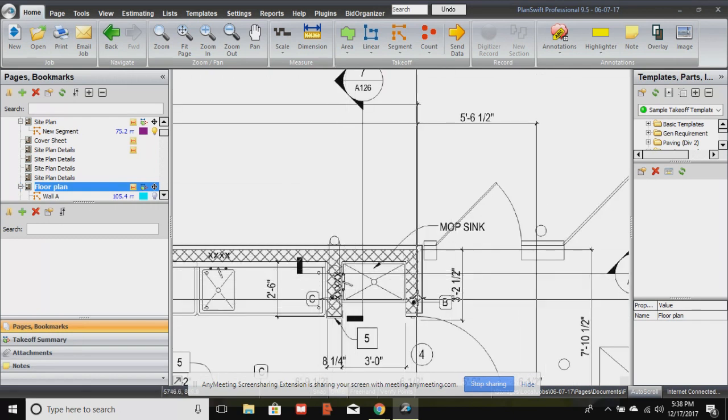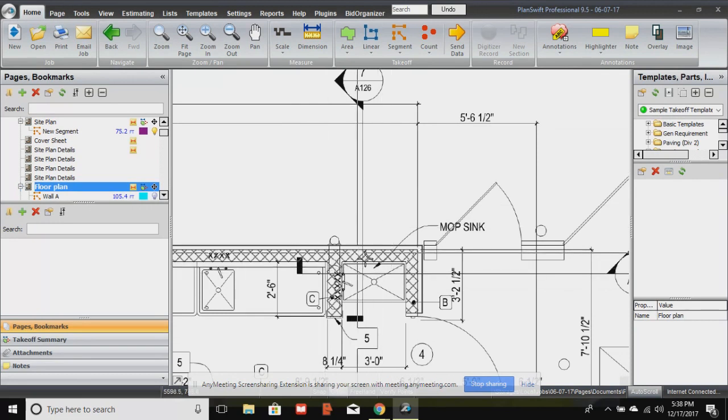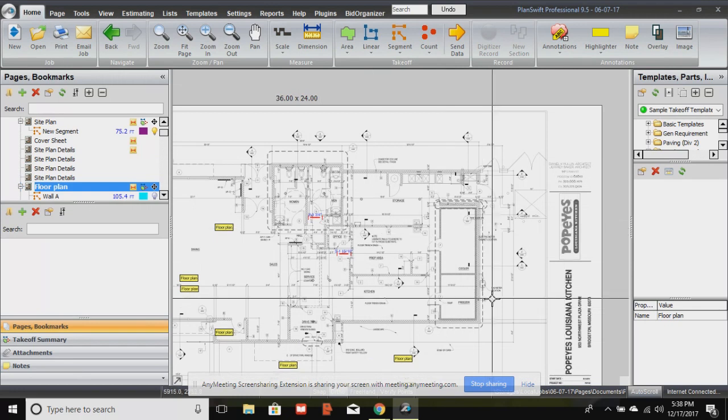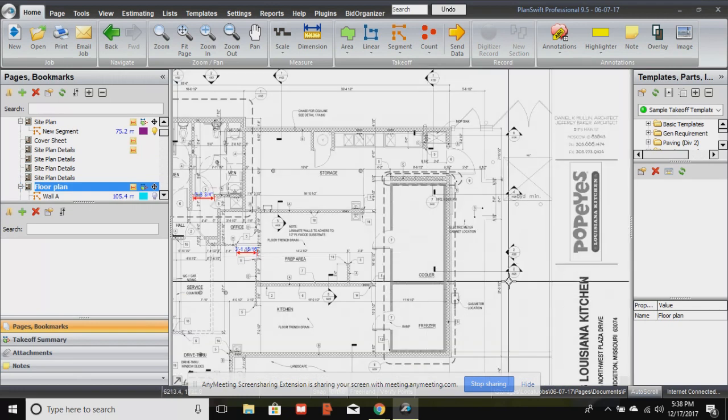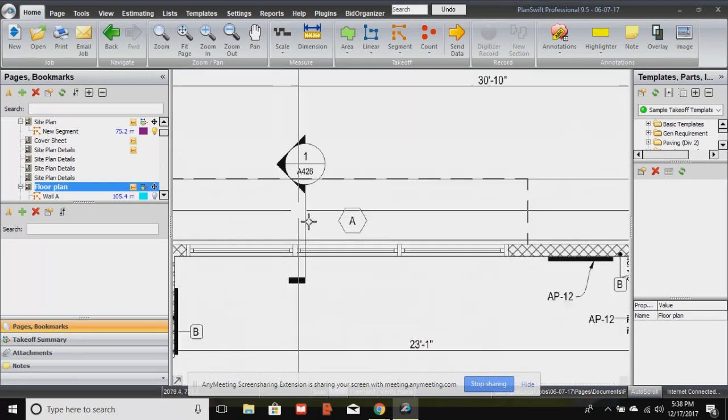And so the architect is saying wherever you see in that section view, you need to apply it to this wall and this wall. You need to apply it to both vertical walls of the mop sink, but not to the horizontal portion, because I have a totally different section view for that. That's why you have your section views. So all throughout your project, you're going to see section views because, again, the architect needs to let the carpenter know the construction is like this here, and then like this over here, and then like this over there. Okay? So let's look at an actual section view.